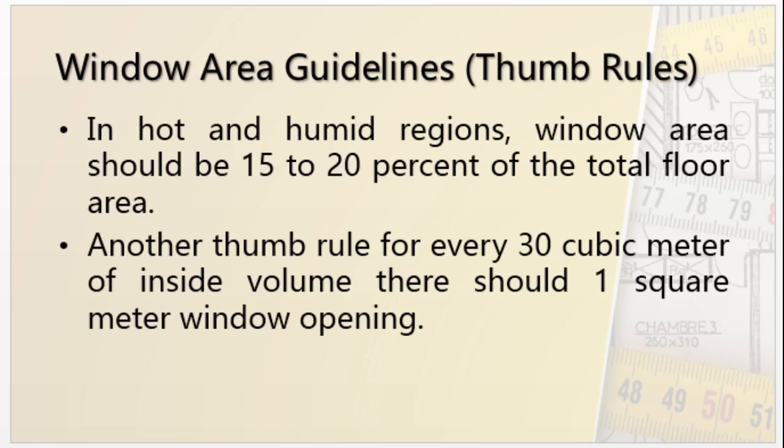That means this should be the 15 to 20% if the region is hot and humid. And in general, in case of any normal place, we use 1 square meter window opening for every 30 meter cube of free spaces.